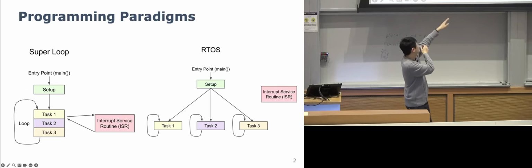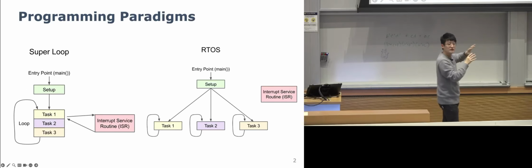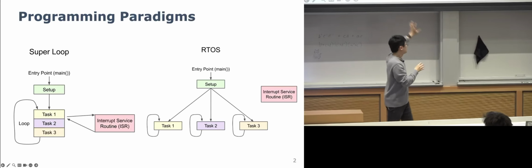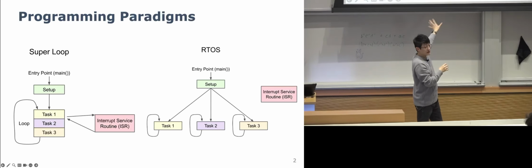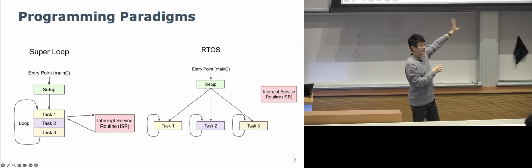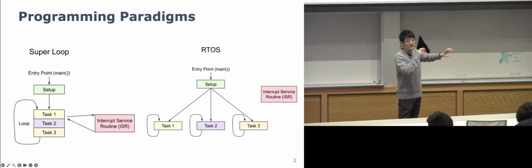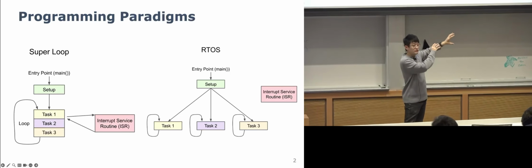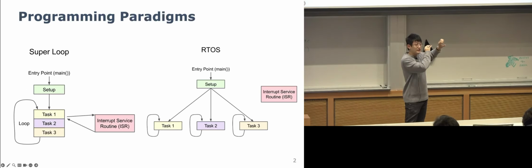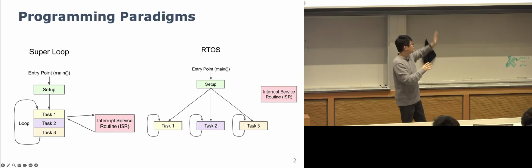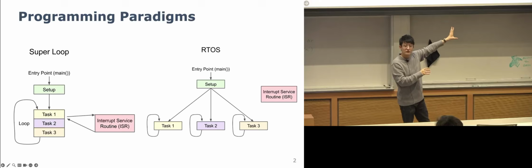If most of these interrupts are just short commands or short instructions, the interrupt approach will probably work very well, could even be better. But if you have a bunch of tasks that need to interrupt each other, and they contain a large set of instructions, so that running one of them might significantly delay other things in the pipeline, then this will be the configuration to go with.